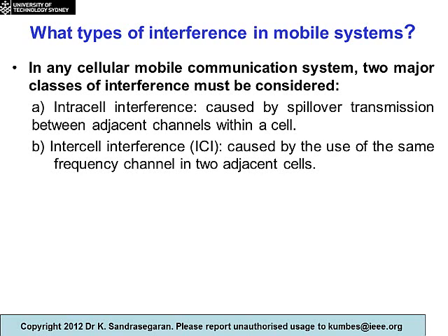Intracell interference is usually considered a very small problem because we are allocating orthogonal OFDMA symbols to users. But intercell interference is a major problem because the resource blocks that are used in a cell can be reused in adjacent cells. So you could have two UEs, especially at the cell edge, using the same resource block, and their transmissions could interfere with each other.